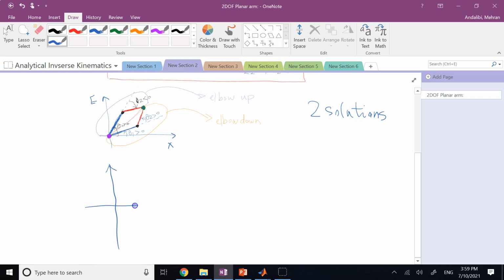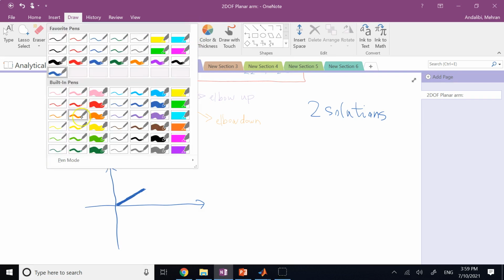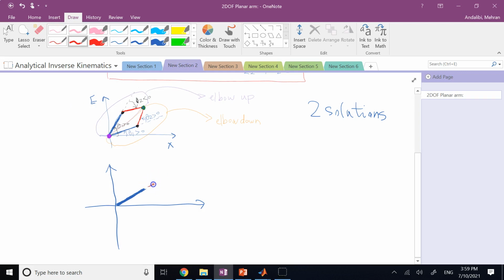Yes. With the very same robot, what is the maximum point it can reach radially? If I ask you, what is the reach of this robot? What is the largest distance, the biggest distance from the base of the robot that this robot can reach. You say, well, the max it can reach is here, that you extend this second member and you make it fully extended like that, correct? And you're right. That is the max the robot can potentially reach. Agree?